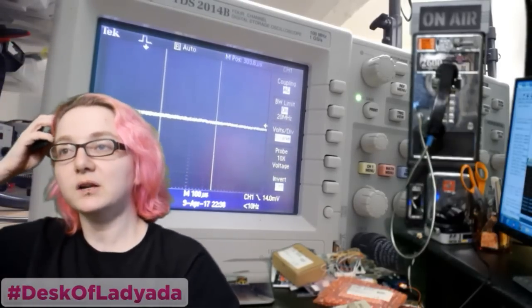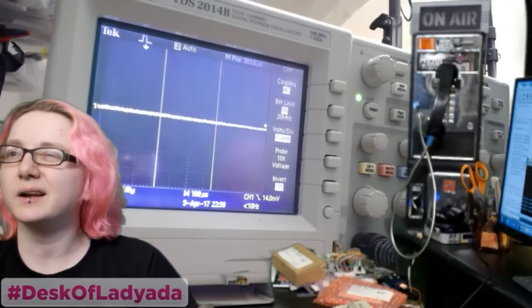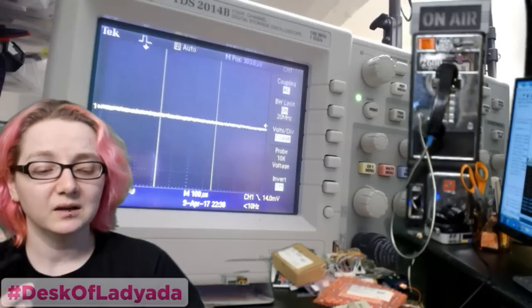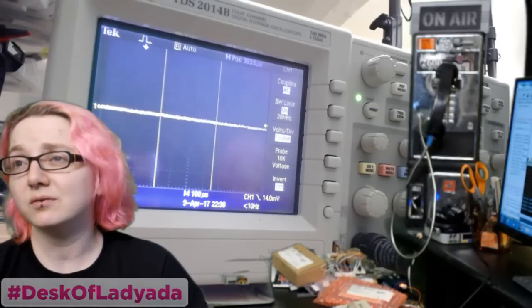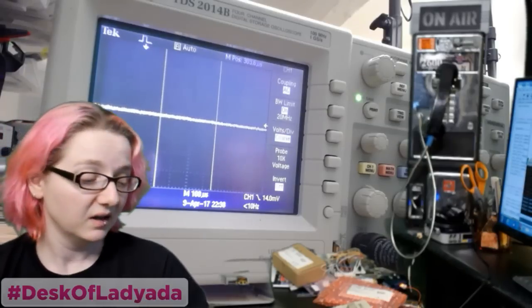console. So the upshot is, if you want to try to do this on your own with just a pin diode and an op amp, you could probably get something working from a couple inches away. But if you want to really have your remote work from up to 15 feet away, you need to get one of these receiver chips. They do the job really, really well. It's worth the 20 cents.